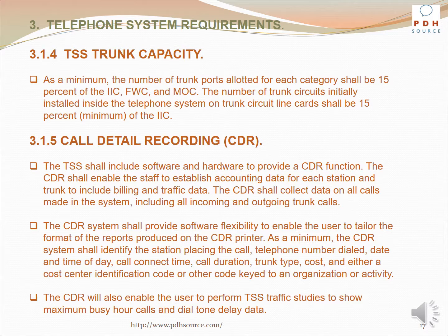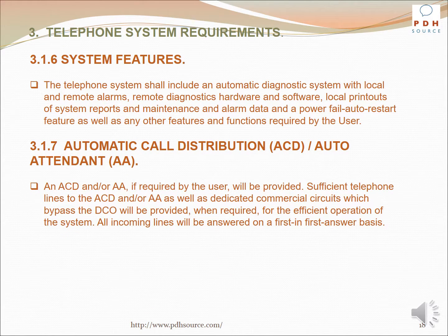The CDR will also enable the user to perform TSS traffic studies to show maximum busy hour calls and dial tone delay data. The telephone system shall include an automatic diagnostic feature with local and remote alarms, remote diagnostics hardware and software, local printouts of system reports and maintenance and alarm data, and a power fail auto restart feature, as well as any other features and functions required by the user.